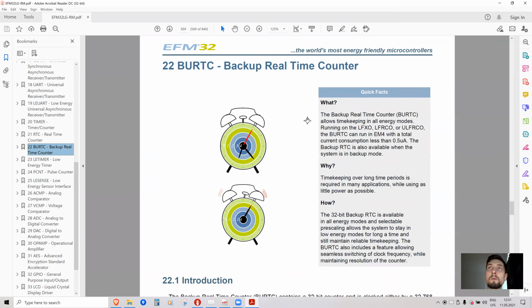So we can go to the real-time clock documentation in mlib, RTC, and just like everything else for this processor, we can use this real-time counter initialization typedef structure, which we fill up with our settings, and then we feed it into real-time counter init, and then it starts to work.